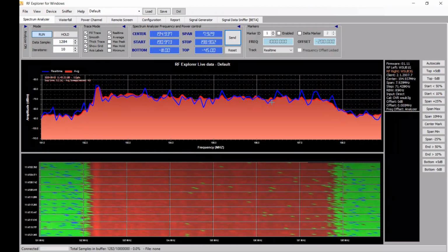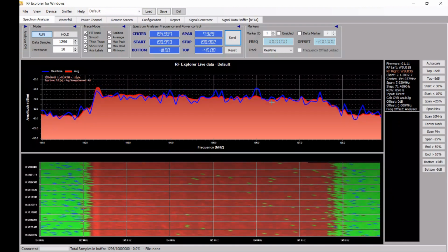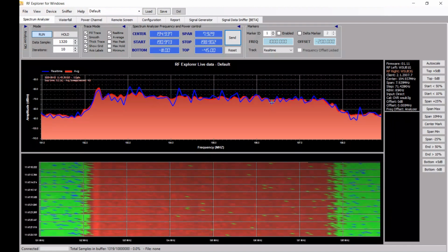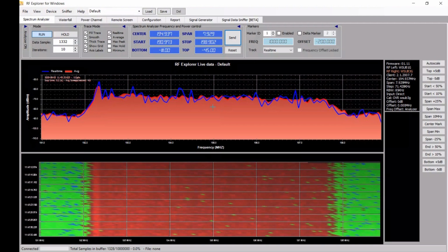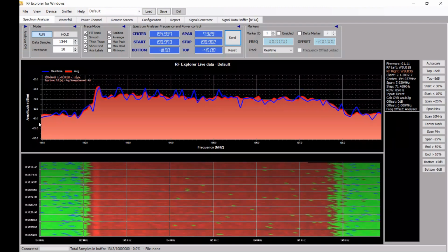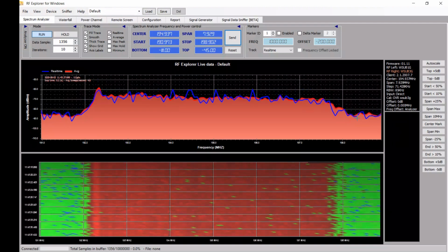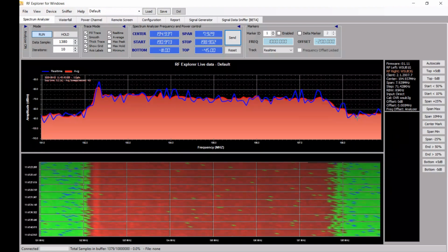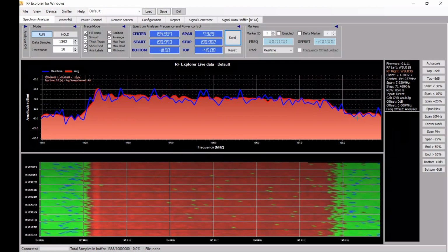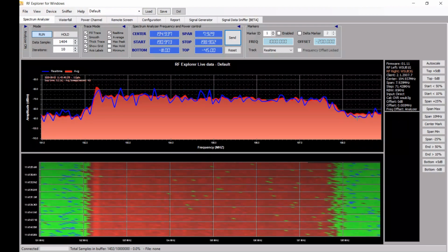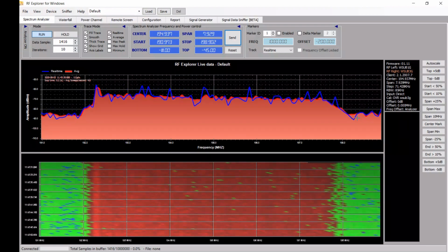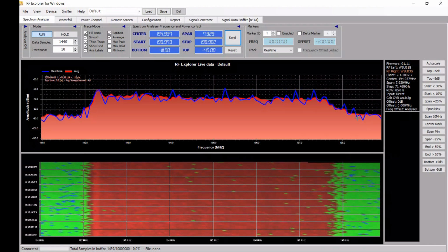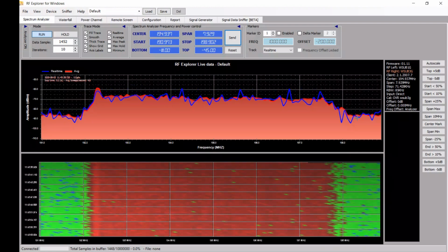And that goes to what an amplifier actually does. An amplifier amplifies. Makes sense, but it also amplifies noise. So we have the signal being amplified here and the noise being amplified here. So why is that important? Well, while signal strength is important, signal to noise ratio is equally or more important in some cases. To receive a signal well, you have to receive the signal, but it has to be above the noise floor a certain amount.